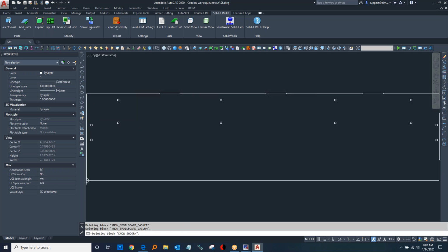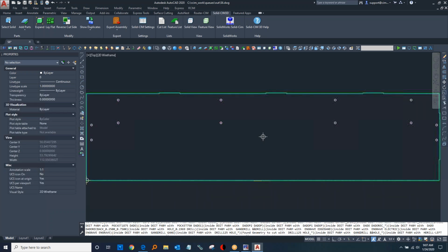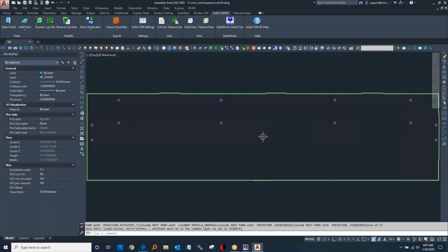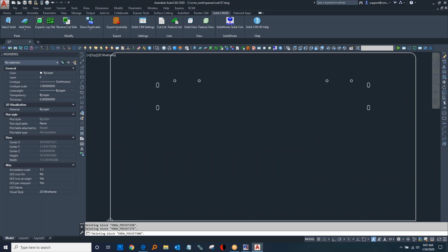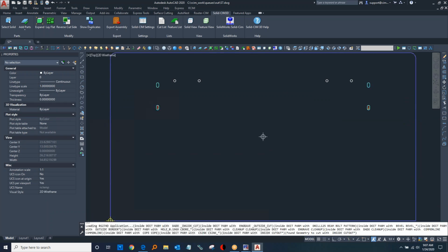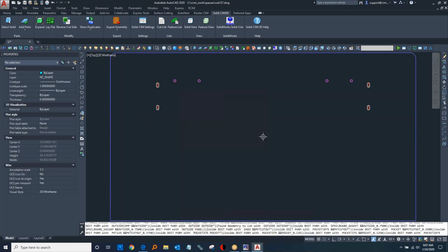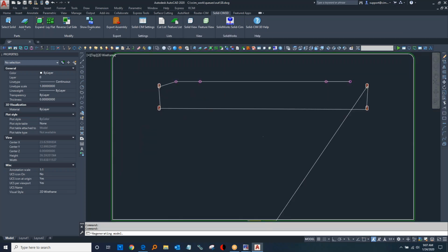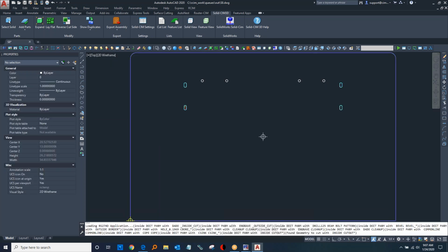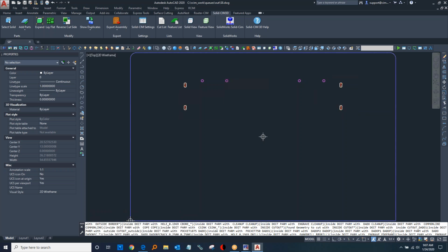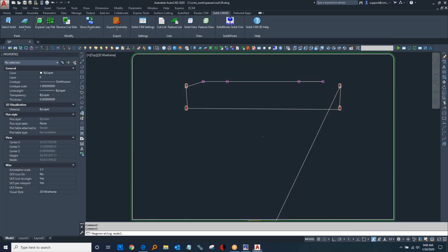Another feature we have is advanced cart control nesting. This is for high volume manufacturing. If you want to run 10 jobs together, you'd get a really good yield, but there might be parts for all 10 jobs on one sheet, and we can limit that. We could say I only want to put 3 or 4 carts on the sheet at a time, and then there's a protection there for yield. If the yield falls below a certain percent, then go ahead and add additional parts onto the sheet. These are some of the advanced nesting features we have there.